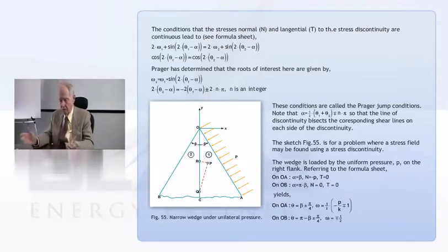And one of the things that Prandtl discusses is what should I assume is the internal normal stress. Well, any engineer would look at that figure and say, I've got compression on the left and tension on the right, along the surfaces. And immediately that tells you which of the choices on the internal normal stress you should take. And this is just a matter of writing down what is obvious and combining it together. And on the next slide,